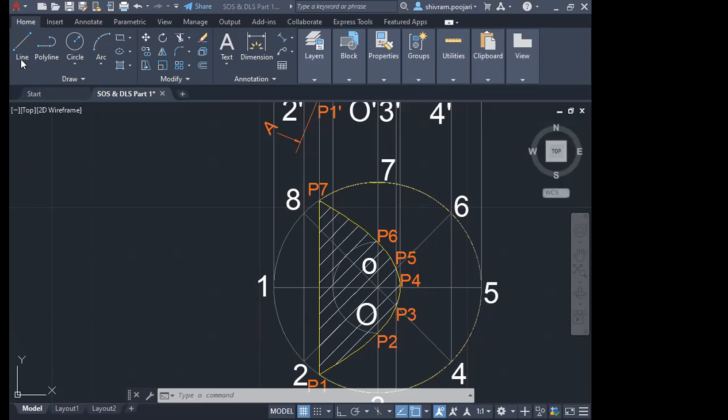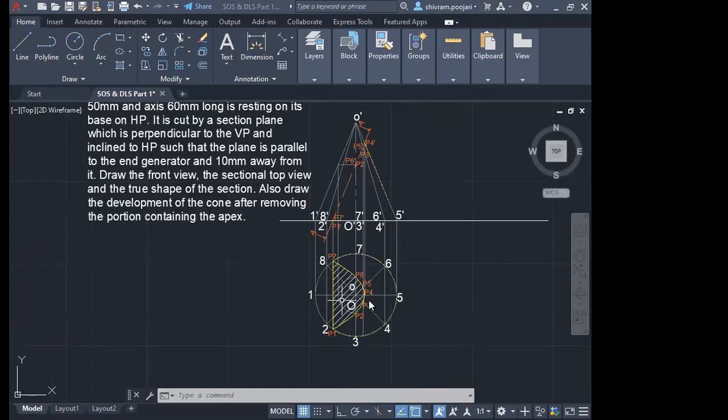Yes, yes. The hatching line represents the sectional part which you are seeing from the top view. This particular plane, as it is a top, we are making it out of the horizontal plane. So the section line is representing the section part of the top view. Hatching line should be medium dark.